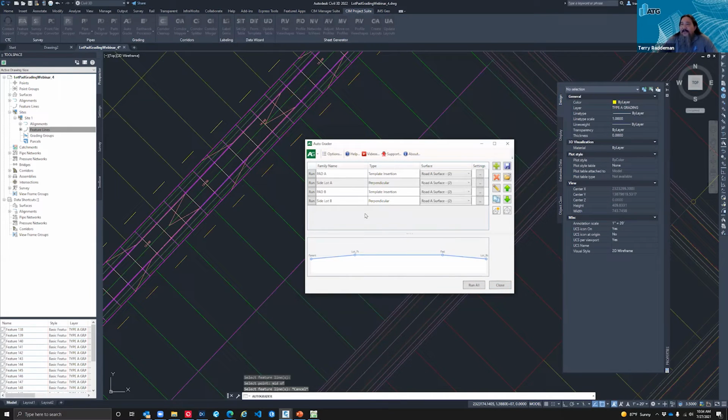All right, so we can create different options. If we were doing this manually, we would create a feature line that is static, and we would assign slopes and PIs to them to develop each one of these lines here. We could probably develop one and then step offset and then move it to this elevation point and have our elevations run. We have a 0.6% slope on our roadway here. And this feature line is actually elevating a bit as well because it was taken from our corridor.